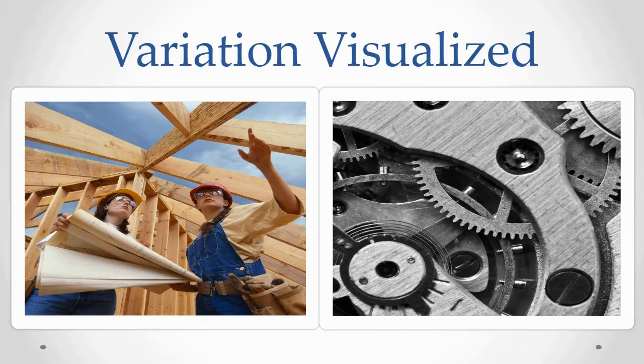For example, in constructing a building using wood frame construction techniques, pieces might vary as much as 1/16 of an inch without causing a problem. But in a different application, like the precise inner mechanism of a wristwatch, the pieces are super tiny, and being off by 1/16 of an inch would be completely unacceptable. In this application, an acceptable tolerance might be as small as 1/10,000th of an inch. It all depends on the application, and skilled engineers need to understand when and how to apply a tolerance to their designs.